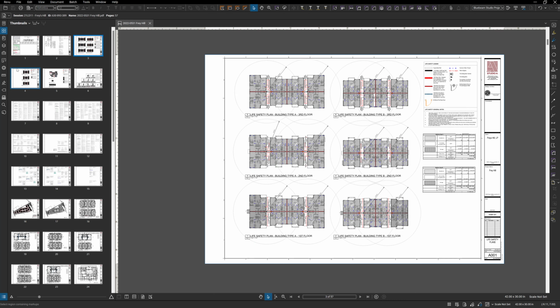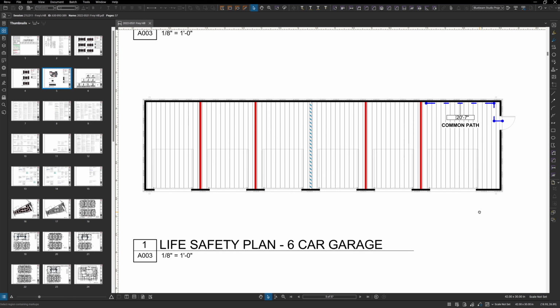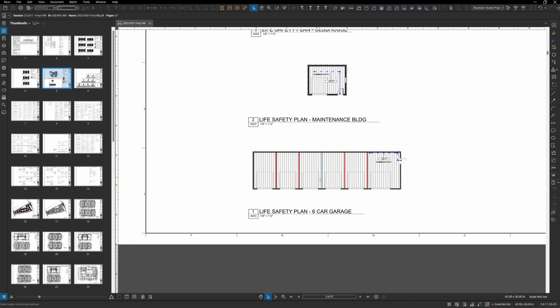Okay. Moving on, other life safety items. This is something that I see often in Kentucky. They want to see the garages. They want at least one fire barrier, and the rest of these can be fire partitions. That's something that will help you. If you go look at one of these jobs, it's an easy way to understand the difference between fire partition and fire barrier. Fire barrier goes typically to the underside of the roof deck versus the fire partitions, which just stop at the ceiling.